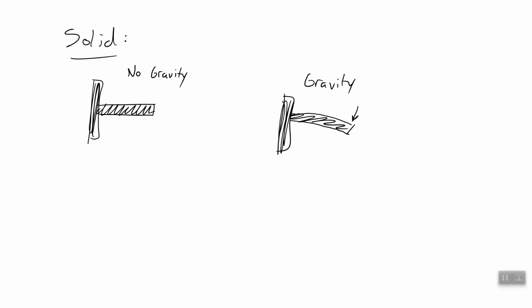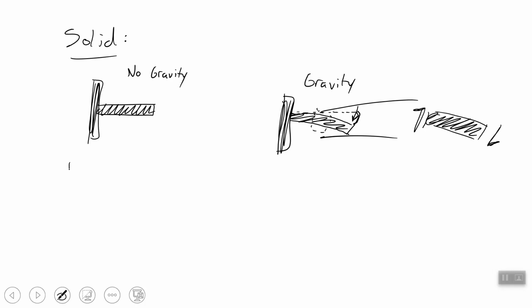We've got shear stress inside of this beam. This is just a little cross section, right? We've got shear stress, and the solid meets that shear stress by deflecting a little bit, a static amount, right? Here was our initial point. We've deflected some value, and then we stop deflecting. A fluid cannot do that.